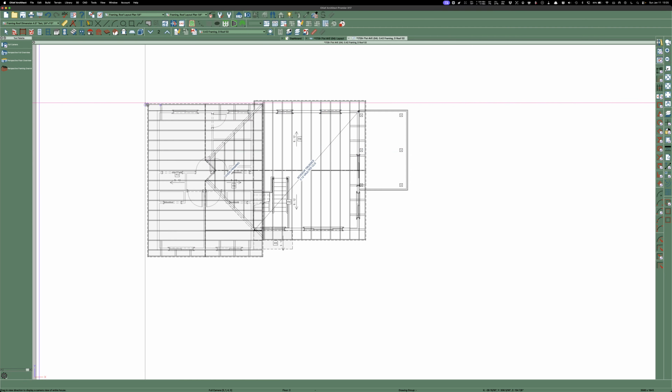Typically, the reason why they use trusses up here is the framing intelligence has been lost, and every builder assumes trusses are just easier and better, and that's not true. The only advantage to a truss is they can clear span longer than you could stick framing for cost. But anything after that, you can stick frame some amazing things.